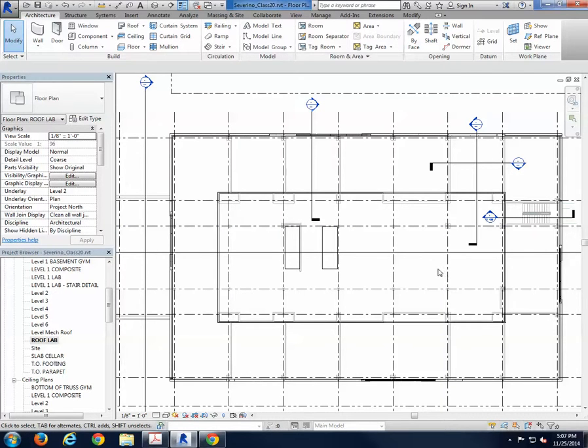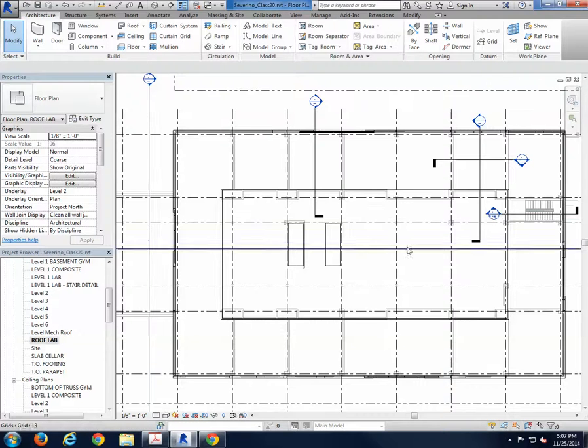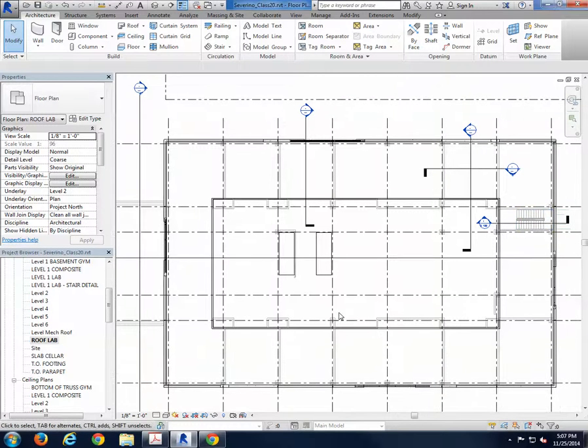A normal design will have made these stairs in the core and it will just have continued to the top. But many other designs I know and I have worked on, you finish in the 6th level, for example, and you do another stair that goes up to the mechanical space, only open for maintenance, no? So you will need to do a little opening, like a shaft opening, and create a little stair that doesn't have to comply with exit conditions or egress conditions, because it's only for maintenance, no?